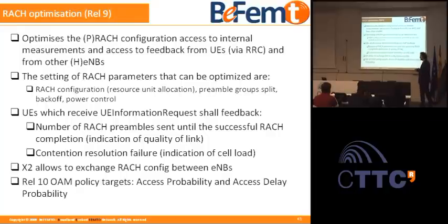And if the call establishment is successful, it determines how many people a base station can take. So therefore, controlling the response to the radio access channel is very important. It gives you an ability to load balance. Because imagine I'm a user, I'm trying to access my eNode B1, which has a very good field strength to me, and I'm saying, I would love to have radio access to this base station, and it turns out that my base station is overloaded, so it just ignores me. It just says, I don't want to hear anything about you. So I figure out it doesn't want to hear anything about me, so I'm going to the next one. So these are the type of load balancing schemes you have.